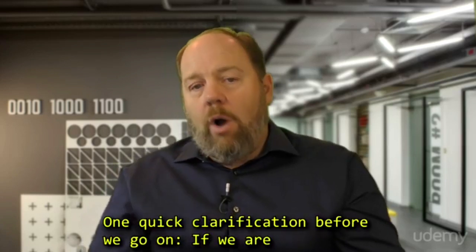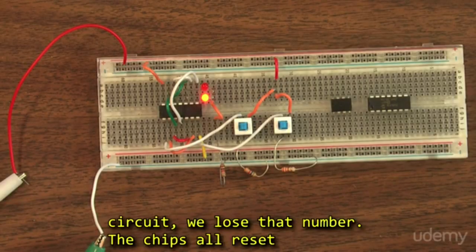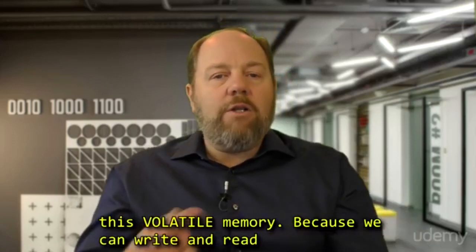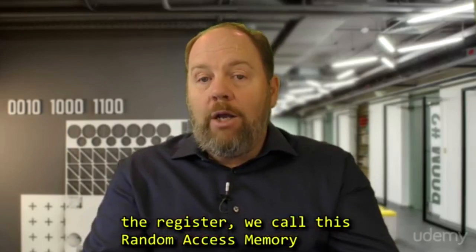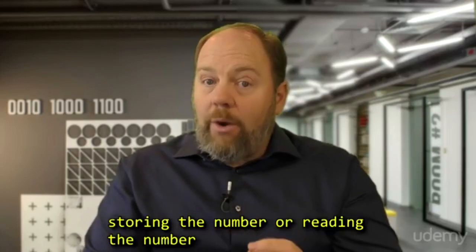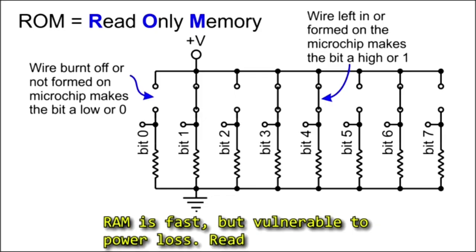Now, one quick clarification before we go on. If we are using these registers as memory to store a digital number, the moment we remove power from that circuit, we lose that number. The chips all reset and turn off because there's no more power. We call this volatile memory. Because we can write and read the register, we call this memory random access memory, or RAM for short, because we randomly access it for storing the number or reading the number from the register. Now, RAM is fast, but vulnerable to power loss.